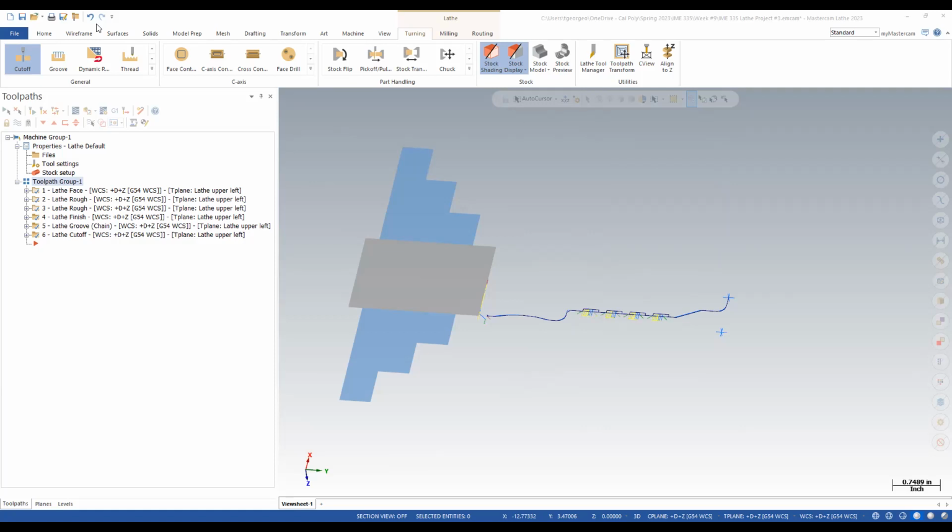So we're roughing back there. It's looking good, right? Why hasn't it touched the top yet? Because we left stock there. I got it there. Now it's grooving. Oh, I had alternate on there. You see that? It's a waste of time. It's alternating sides. It's an extra time to move from this side to that side, right? Why would you want to use that? I don't know. There's that option though. Is that in roughing? Yeah, it's in roughing. They're alternating sides in roughing.